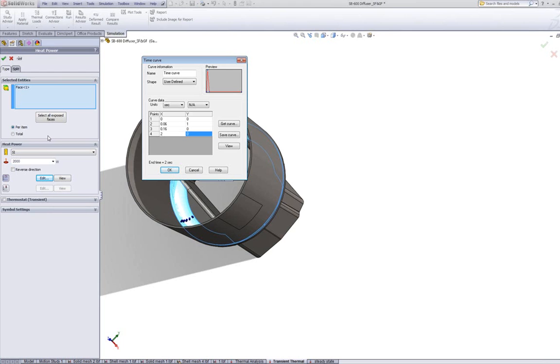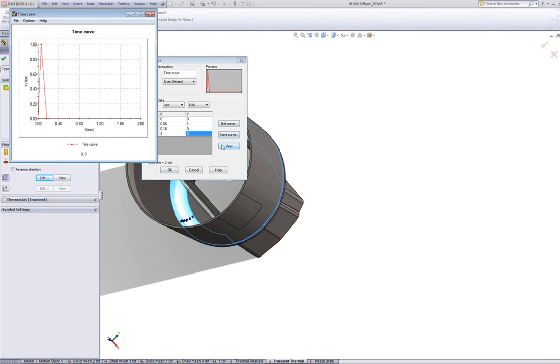So effectively what we're doing is we're giving it a time dependency, and we're telling this thing to spike up. If I can view my plot, we're basically taking it and we're increasing the magnitude of the flash. We're representing the heat power due to the conduction of that flash to the plastic, and it's peaking there at that particular time. It's going back down to a magnitude of 0 at 0.16 of a second.